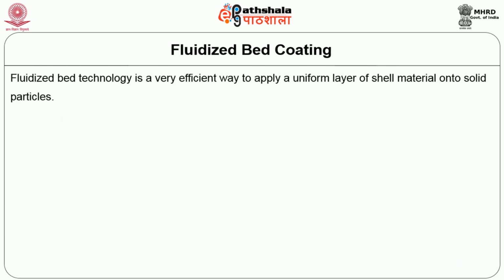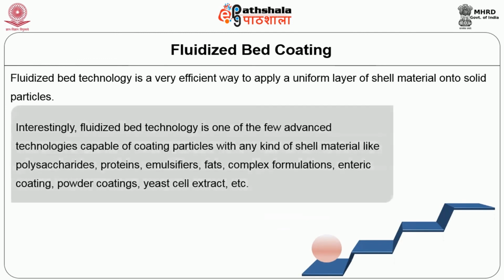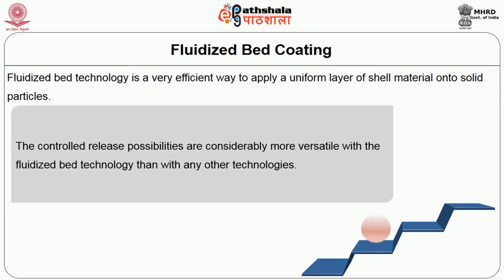Fluidized bed coating. This technology is a very efficient way to apply a uniform layer of shell material onto solid particles. Interestingly, fluidized bed technology is one of the few advanced technologies capable of coating materials with any kind of shell material like polysaccharides, proteins, emulsifiers, fats, complex formations, enteric coating, powder coatings, yeast cell extract, etc. Therefore, the control release possibilities are considerably more versatile with the fluidized bed technology than with any other technologies.